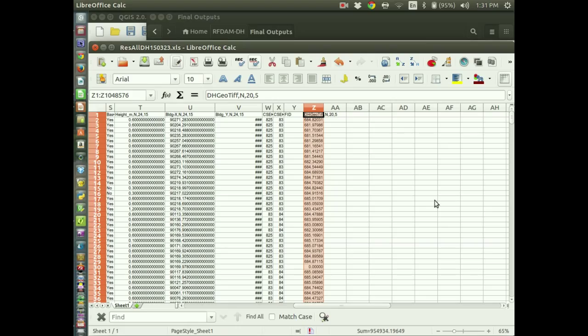Normally, a lot of times, the LiDAR surfaces, the DEM GeoTIFFs, are in UTM coordinates. And provincially, the municipal coordinate system is 3TM, so they don't fit. You have a program that converts it over?